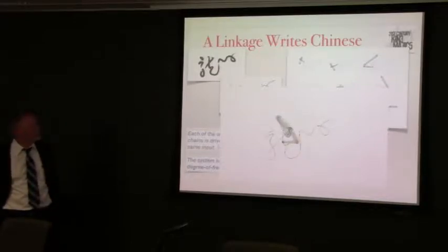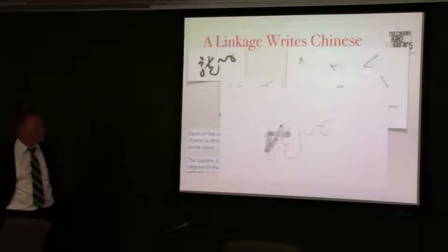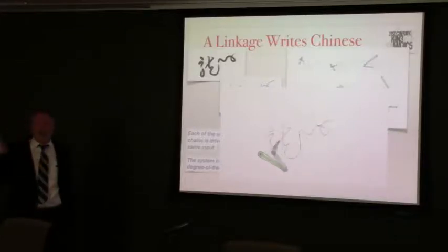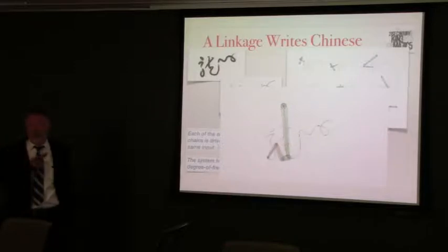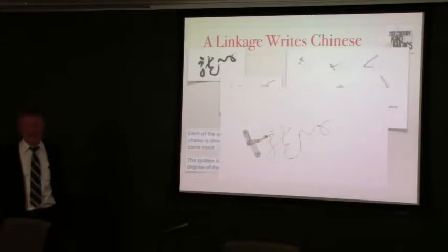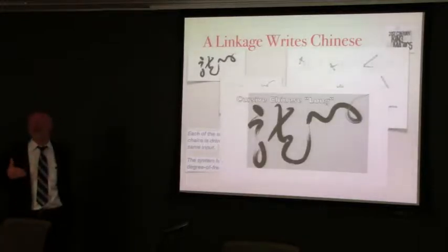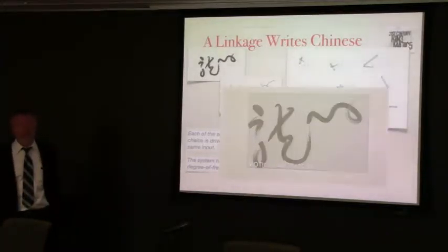Is there ever a problem with these linkages locked? All linkages lock, right? I always have that problem. If the linkage locks, it's not useful to us. Do you know what I mean? So one of the procedures that we go through when we analyze these linkages is to make sure they do not lock, or jam, is what we say.